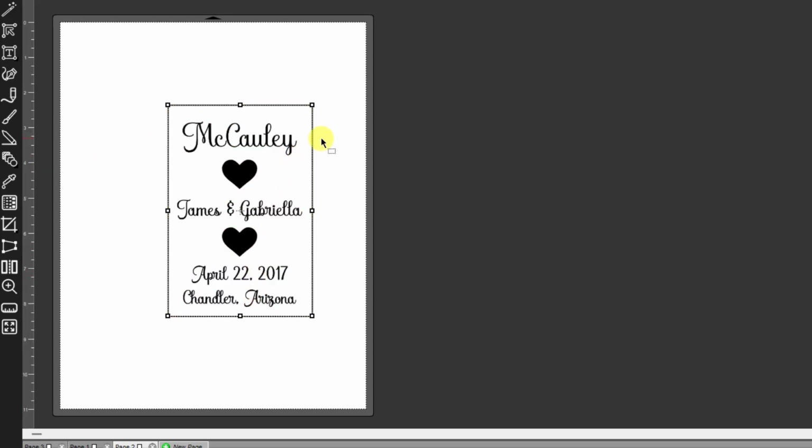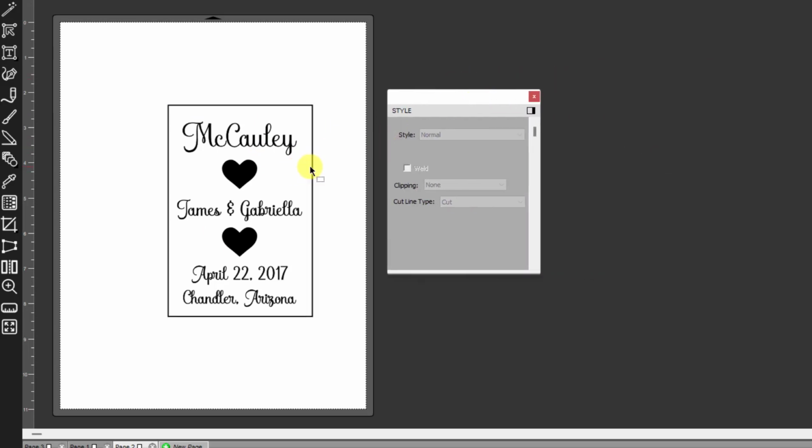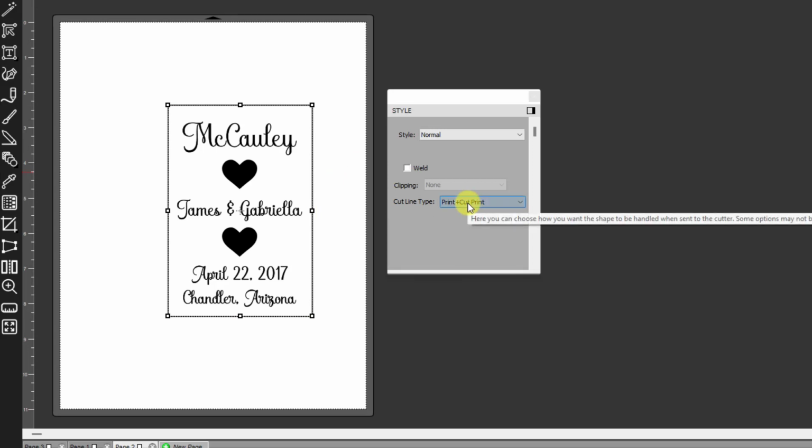did the design, and then before you get ready to engrave, one of the things you might want to do is select this outer shape that you're not going to send. This just represents the item you're going to be engraving on, and set it to print plus cut print, because that way it can't possibly be sent to the cut window.